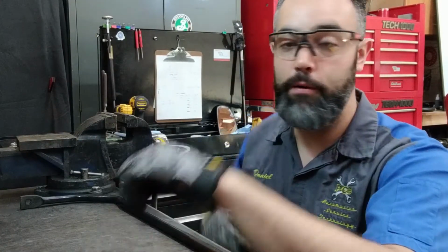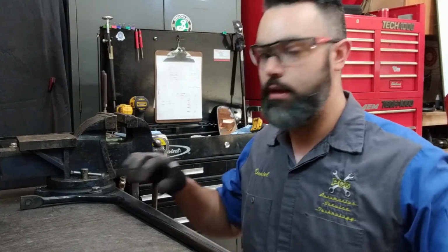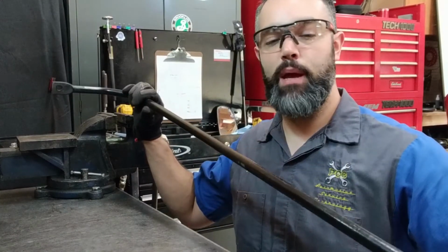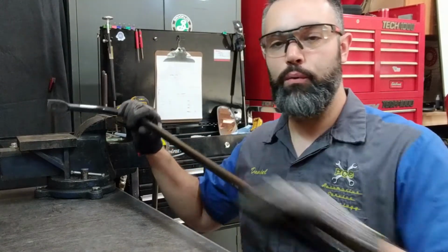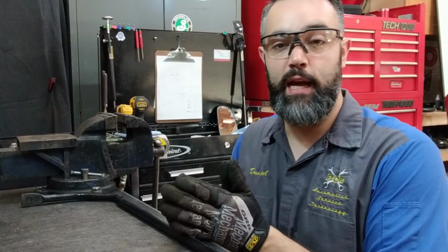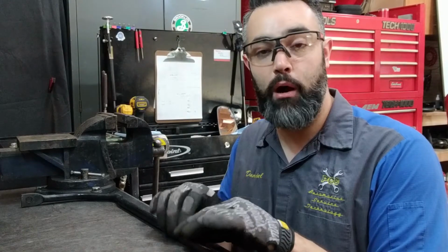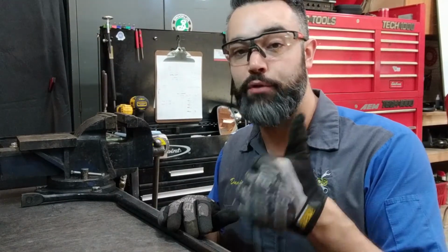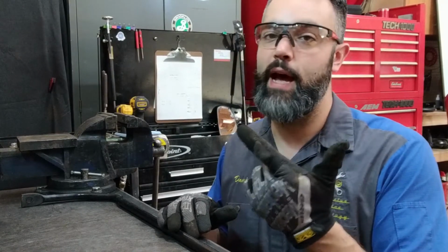On the example of the Jeep, where the end links have been modified, you disconnect the sway bar for off-road and reconnect for on-road. Newer vehicles have a feature built into the sway bar system. In between the two halves of the sway bar, there may be a separation with an electronic disconnect partway down the sway bar. Also, these can be hydraulically activated or electronically activated.